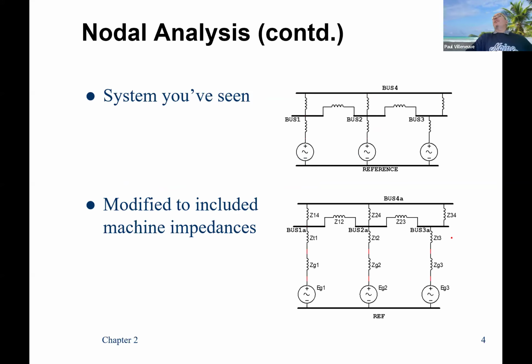They're always called buses. And we can see that we have 3 generators, and they're cranking out power to a common bus. And then that bus may or may not be connected to anything else. Over here, we see that it's not connected to anything else. But in reality, you're probably not just going to connect 3 generators together with no load on them. That wouldn't make a lot of sense. And so then we're going to tweak that a little bit, because each generator has an internal impedance. Anybody know why generators have an internal impedance?